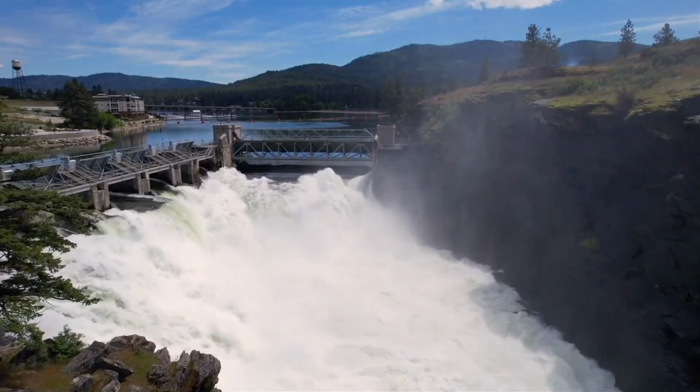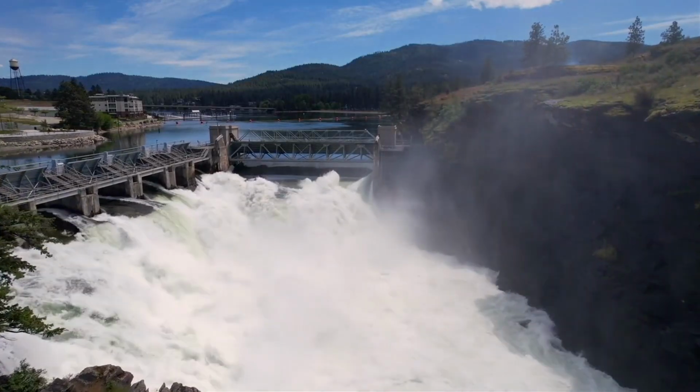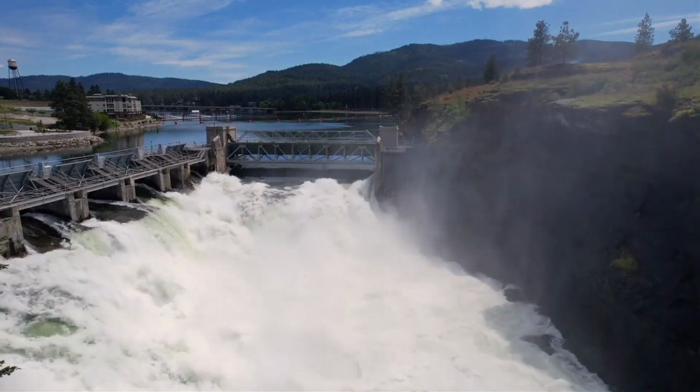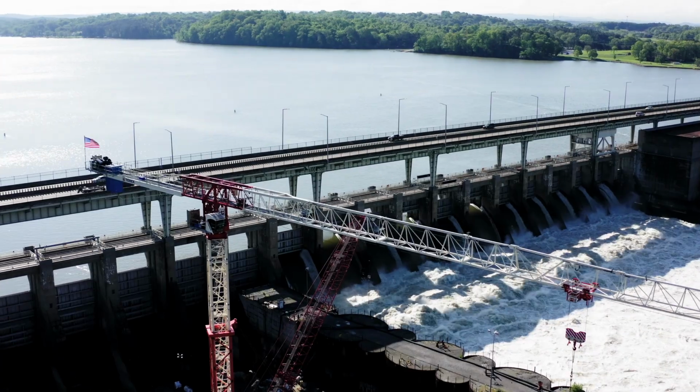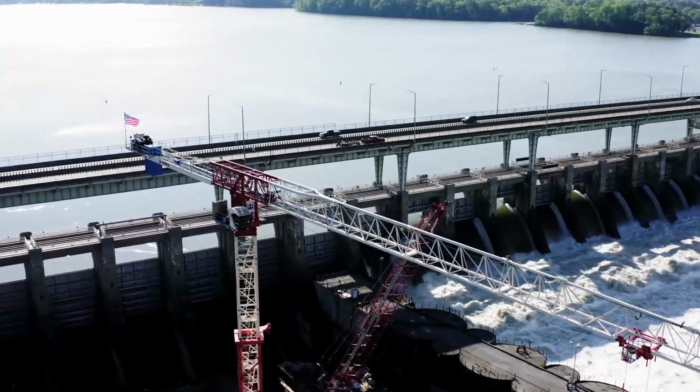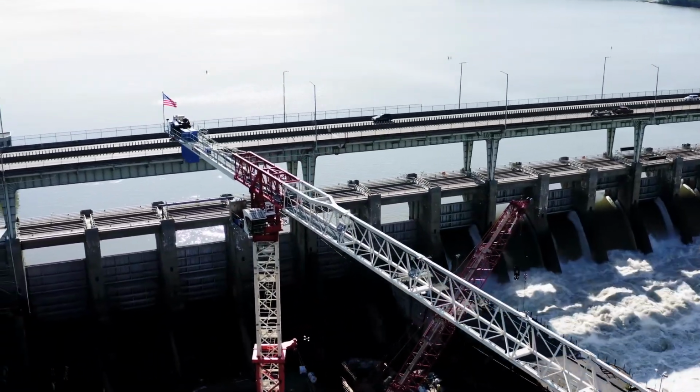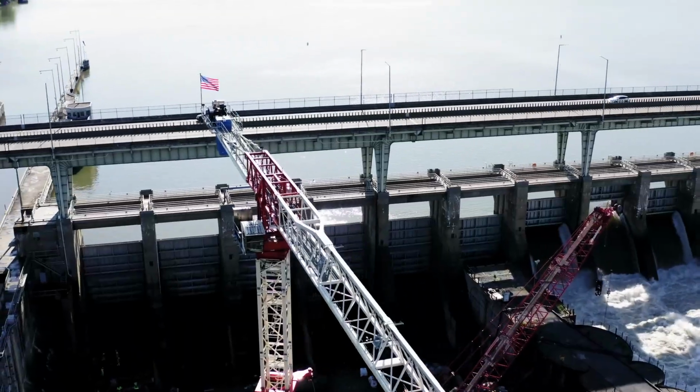If the spillway cannot safely pass the design flood, engineers increase its width or capacity. So the key takeaway from this is that sizing a dam spillway is not guesswork. It requires a combination of hydrology, hydraulic engineering, reservoir analysis, safety evaluation, and cost consideration. A properly designed spillway ensures that the largest floods can pass without damaging the dam.